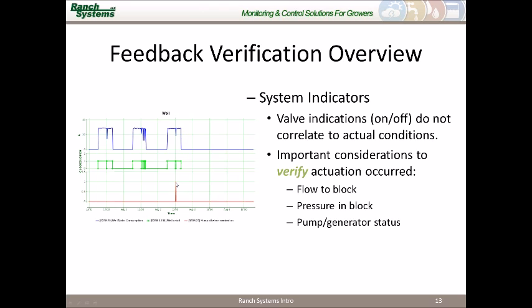The other thing that we've done as well is we know that in this particular instance they have a water level sensor at a tank, and they would like to irrigate during the day and have this tank refill. So what we do is we automate the refilling of the tank and the irrigation system there. When the water level drops to a certain level, the pump is turned on, and you can see that the pump is turned on and it starts to fill the tank.